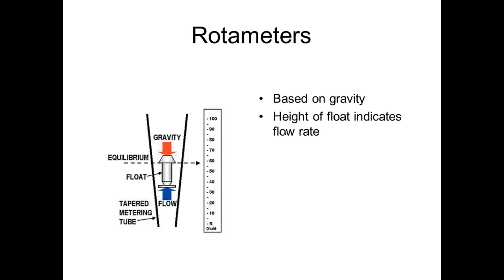I've seen that. Yeah. They're very, very popular on swimming pools. So if you've got a big swimming pool, that's what we used to do. We had a community pool that I was responsible for, and they had a flow meter that did this same thing. That's how you could tell when your sand filter was getting clogged up: you'd look at the flow meter, and if it dropped below a certain level, you'd come in and backflush your sand, try to clean it out.